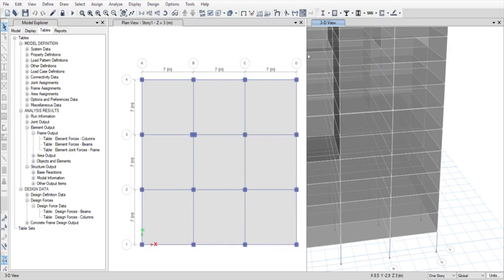Yeah. Now close the tab. Now select the foundation, and I have to give 2 meters of offset. So edit areas, expand or shrink areas, offset value of 2 meters, that is 2000 mm. Okay, you can see the extended area.